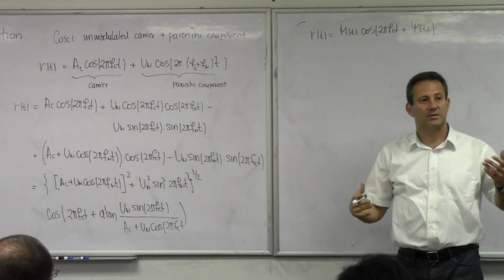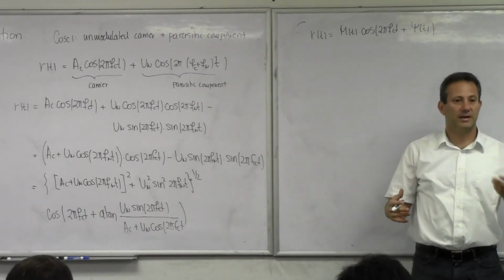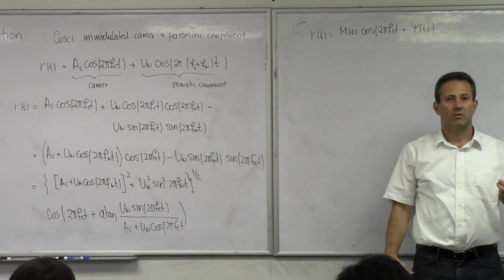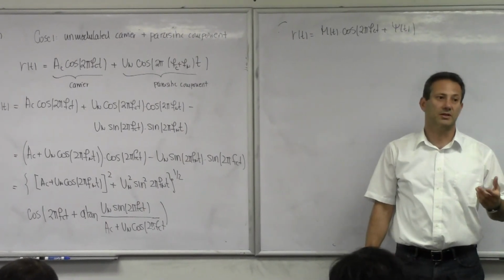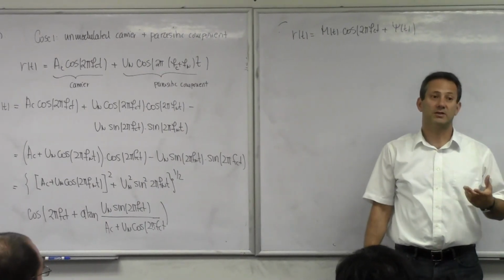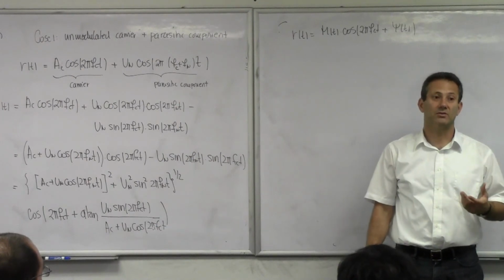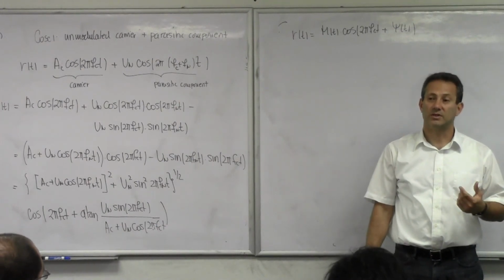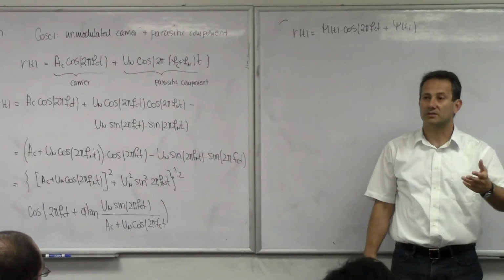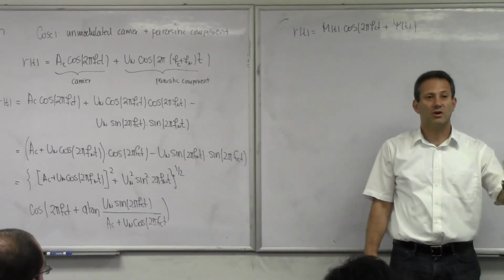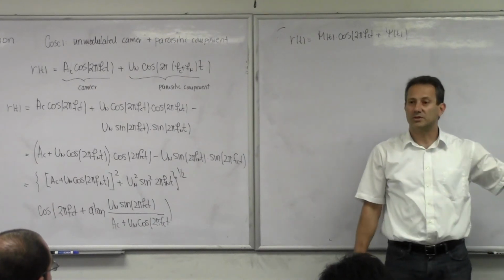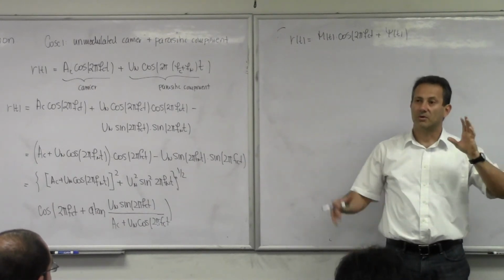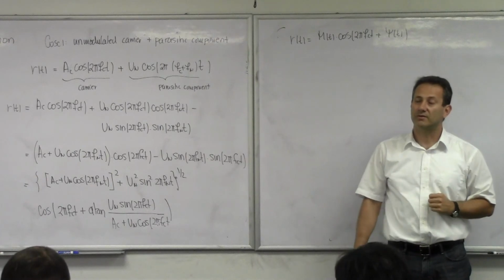Now, the FM receiver is smart. It knows where the information is. Where is the information for an FM receiver? Is it in the magnitude? No, the receiver knows that whatever is changing the magnitude is not the signal. It has to be noise. So I'm going to ignore the changes in the magnitude, and I'm going to try to demodulate just whatever is in the phase.